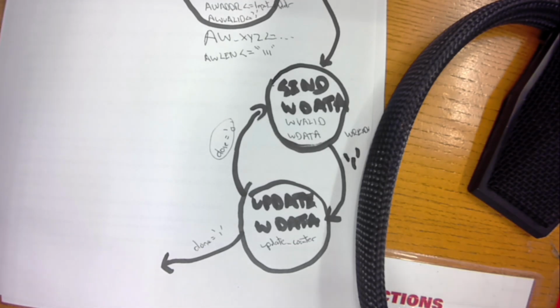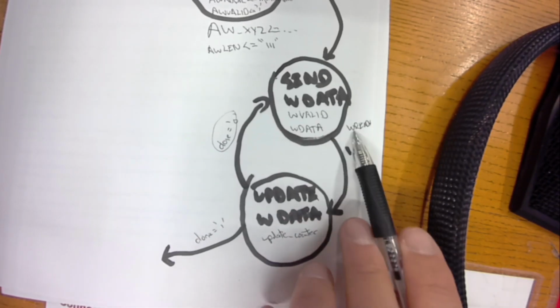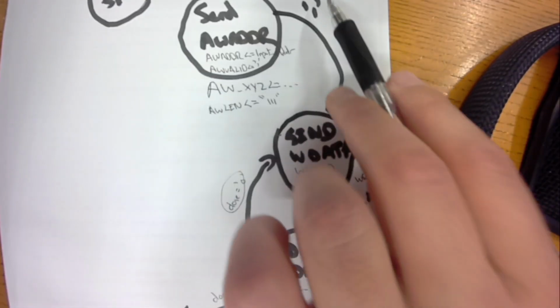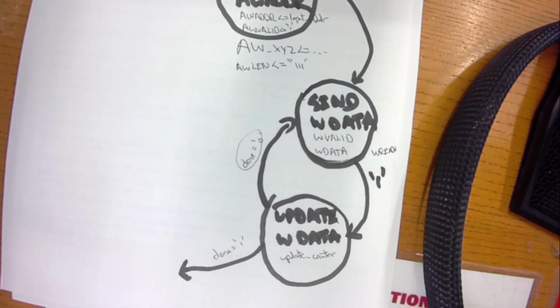But when testing it, I think this becomes a little bit trickier than a lot of things that you would normally test, where you can assume everything's really synchronous. A really good, quote-unquote, good test bench would also be testing all of these receiver side signals, all the ready signals. So you'd want to have a test bench that waits 20 cycles before it sets AW ready or W ready here, so that you can check that your state machine actually is able to deal with a pause, with a wait state that gets inserted into the system. That's a little bit harder to do.